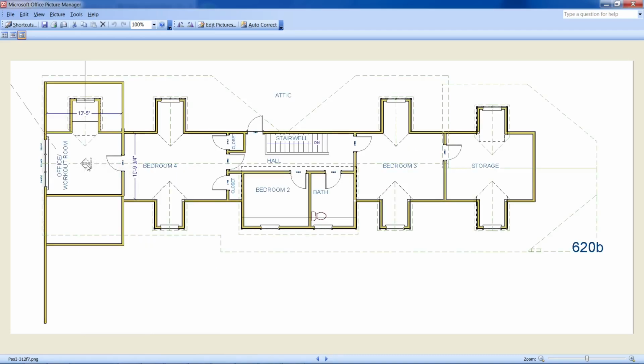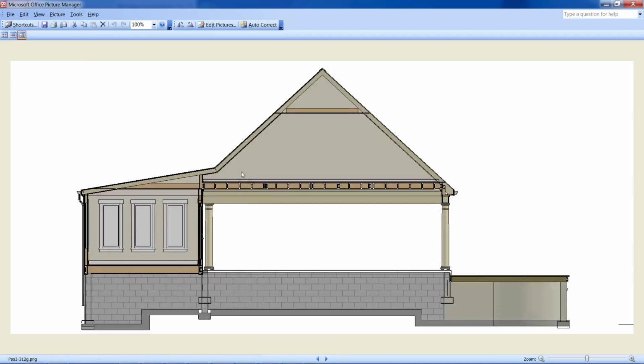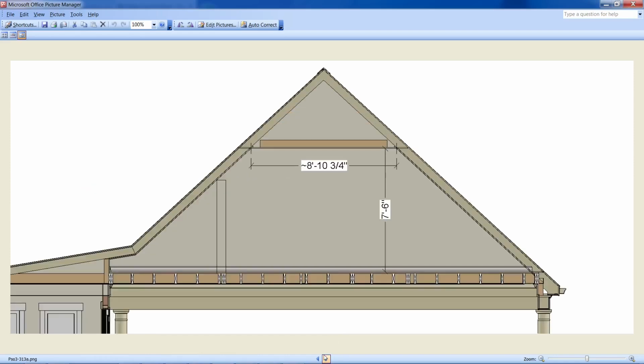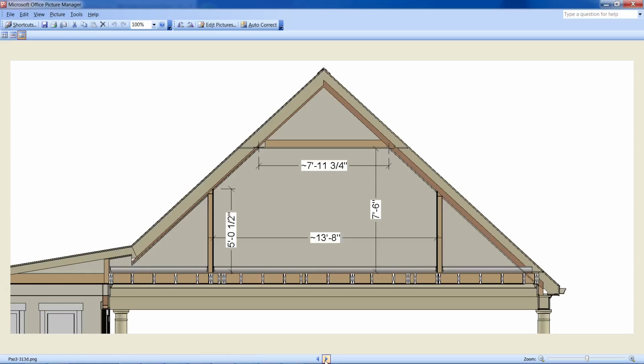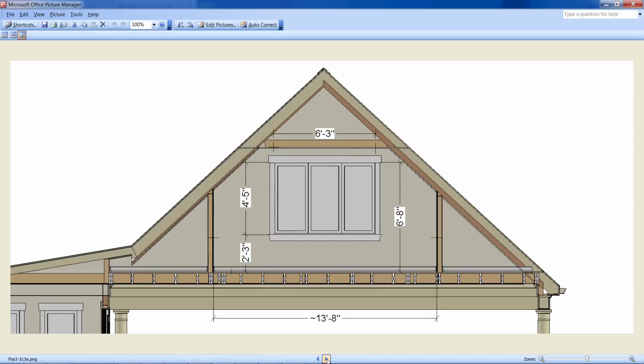And then I'm looking at this section 54 through there, that cut. This is what you have, that big long 26 or 28 foot run here. And when you keep the ceiling at 7'6", you have that 8 foot across the ceiling, 7'6", and that's your current ceiling, around 7'6", 89 and something. So put in the knee walls. If you put in the knee walls at 5 foot high, then you end up with 13'8" wide, and with this bit up here. And then obviously a window.